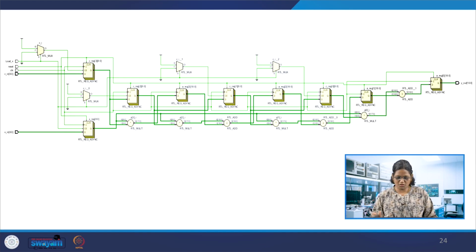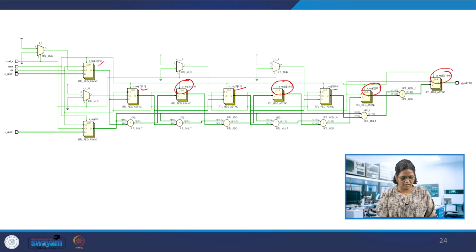So the realization, the synthesis process, results in the technology schematic. Here we have the C-Reg, all the coefficients are given, and these are adders having the registers 1, 2 and 3 here, and then 4 adders here. Then the x input and the realization, which is simply the diagram: you can see all the inputs, load x, reset, clock and c input. X in is over here and you'll get the output y. So this is the technology schematic after synthesis.